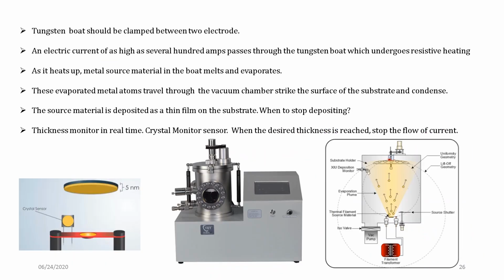And this is the same thing here again, like how the tungsten boat is clamped, and you send electric current over here. You have a crystal sensor. Why is it a crystal sensor? It gives us an idea of how thick the film is. So whatever amount of material is getting deposited here will also get deposited here.